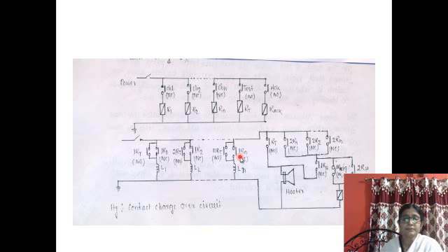And for the audio signal, this is the hooter. For the audio signal, there are contacts 2R1, 2R2, 2Rn. So for n number of relays, there are second contacts, each connected to the hooter signal, so that the audio signal can be produced.